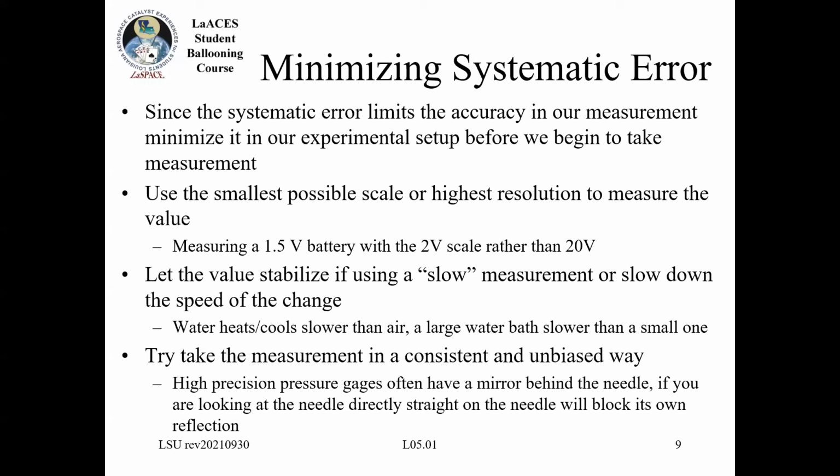Because I could easily stick a heat gun and put the temperature probe and a thermometer in the stream of the heat gun, right? But that air is going to rapidly heat and cool much more quickly than the water, right? So it's going to be really hard to get an accurate measurement and also get a consistent temperature within the volume occupied by my thermometer and my temperature probe.